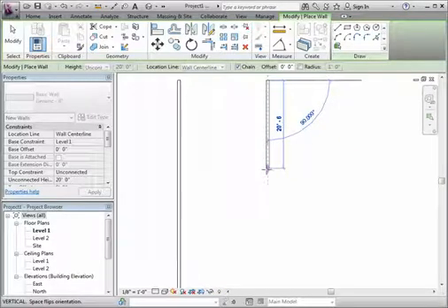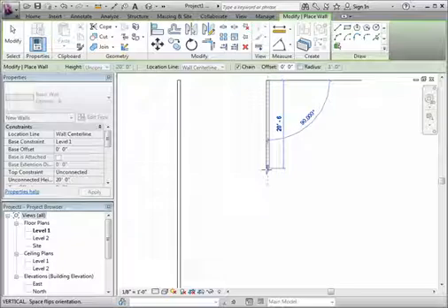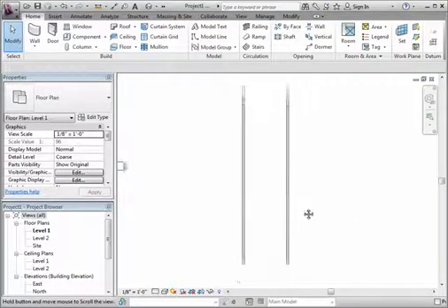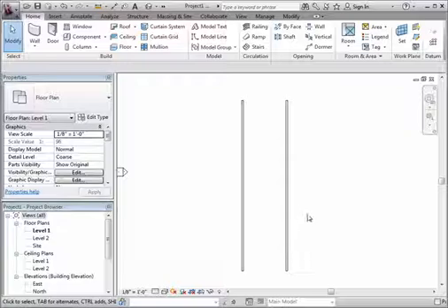And this time, instead of dragging my cursor, there are two things that are happening here. You'll notice that the 20'6" and then the 90 degrees, both of that text is actually blue, which means that it's active and editable. So what I could do right now actually is type 80 and hit enter. And it will actually give me an 80-foot long wall. And maybe those are a little bit too long. Let's make these 60 feet instead.